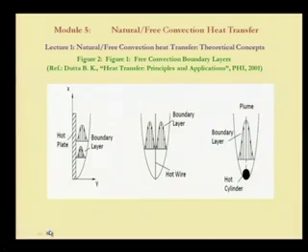So, there will be a flow of the fluid, and this is nothing but natural convection or free convection, and this flow happens due to the application of temperatures. Somewhere it is a hot place, somewhere a cold surface, and the surroundings. So, the temperature difference between the surrounding fluid and the plate is of importance, and because of that there will be a net movement of the fluid particles, which is nothing but the flow or convection of the fluid elements.